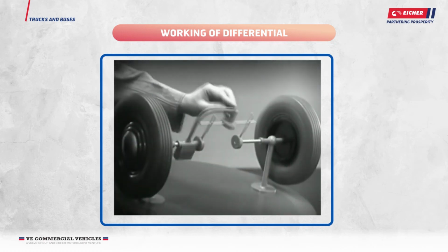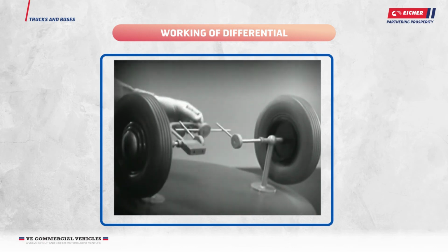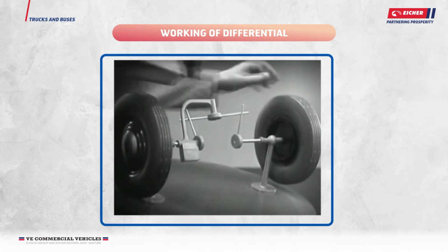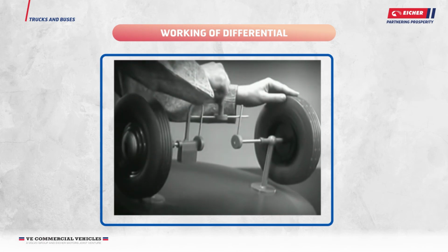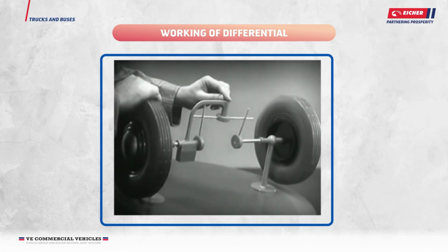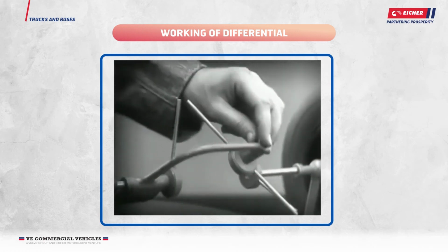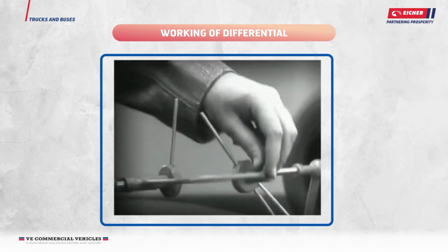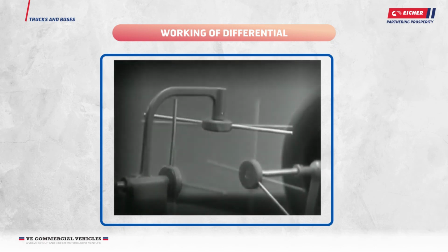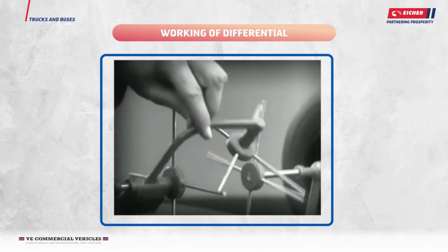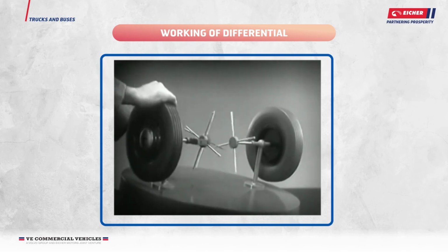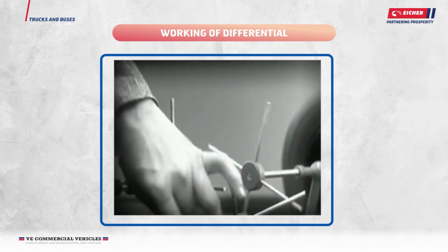Now, the bar can still turn both wheels at the same speed. And because it pivots, it lets one wheel turn even when the other is stopped. But if turned too far, the bar will swing around until it won't drive the spokes that turn either wheel. We need another crossbar and more spokes to carry on the job. When we stop one wheel, the crossbars will continue to push the spokes of the free wheel around.